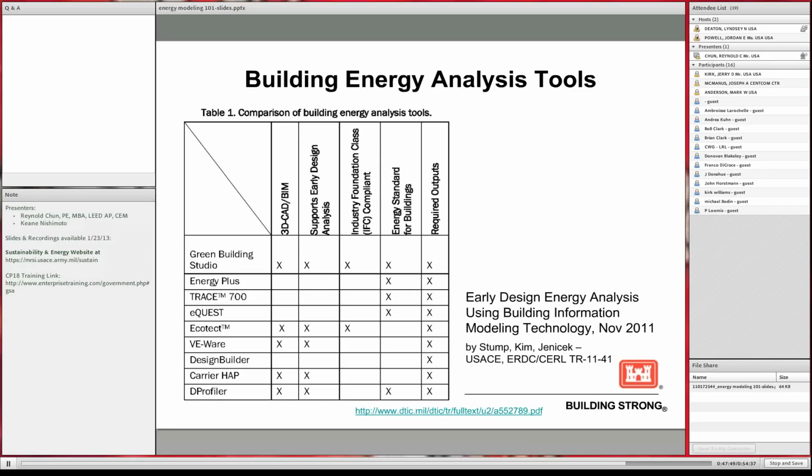I think what we're trying to do for the COS facility types, the standardization facility types, is that they have a footprint, they have a floor plan, and being instructed to run energy models for climate zones, for the worst orientation, and then we could come up with a number that the team then has an idea to look at, and if we change, for example, the R value of the wall, we can then know how would it impact the building.